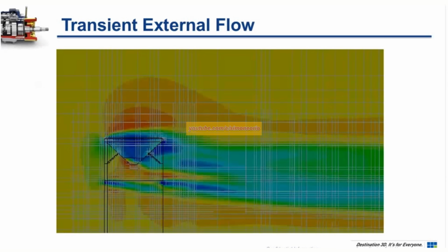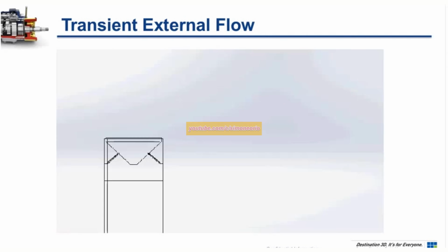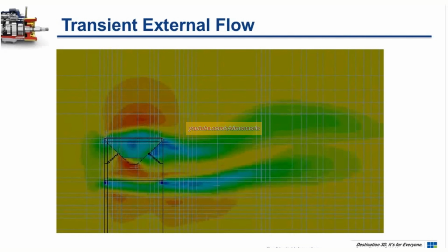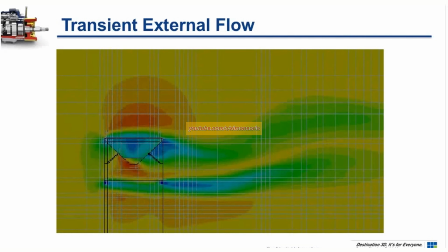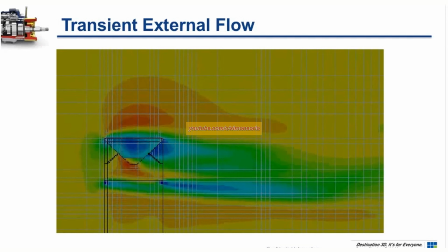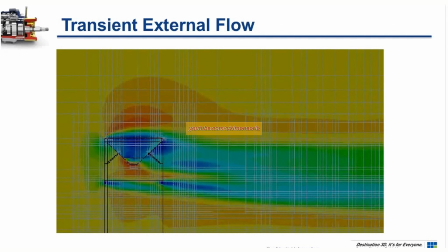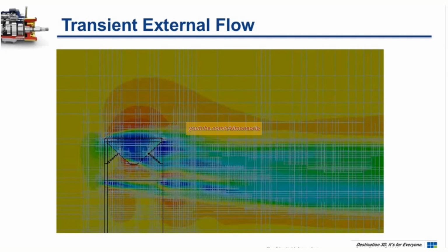And here's an example. So this is a video of the solution. And the gray items are the cells. And we'll see that as the model is solved and the high gradients of pressure or velocity are being created, our cells are splitting in the areas of these high gradients. This way we don't have to know exactly where we need to refine the model.